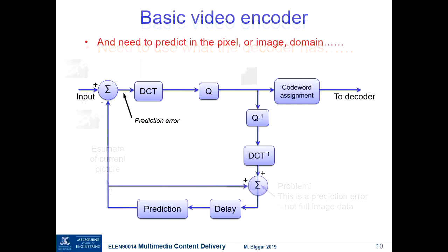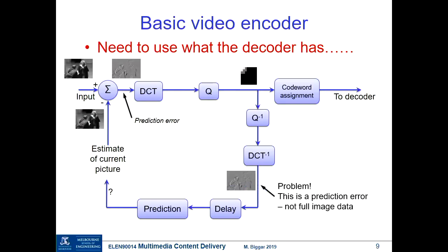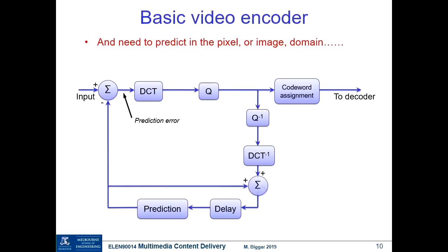If it's not completely clear, just wait. We went through the logic in the discussion about DPCM, but if it's not clear, tell me. The scenario I was presenting to you was if we have to use the quantized data to form our prediction, is it simply a matter of taking that quantized data, getting back to the pixel domain and using that data directly? Well, no, because this is not going to predict that. This is a difference picture. We need to get back into the pixel domain. We need to add that to our previous picture to generate the prediction, and that's achieved in the same way as we saw the prediction loop in DPCM.